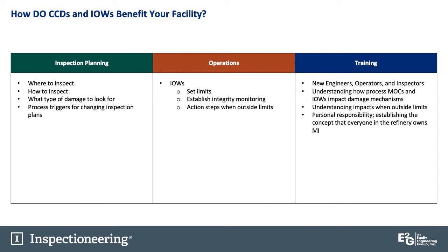As far as training, though, it provides understanding of how process MOCs and IOWs impact damage mechanisms, understanding impacts when operating outside of IOW limits, and personal responsibility, establishing the concept that everyone in the refinery owns MI. So we should be communicating to make sure we're properly addressing our MI risks in the refinery.